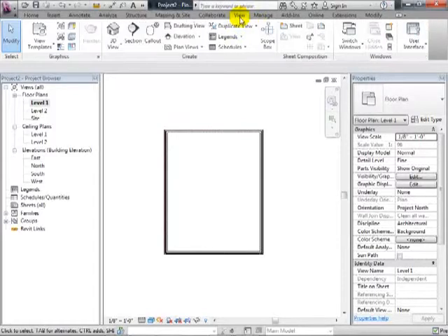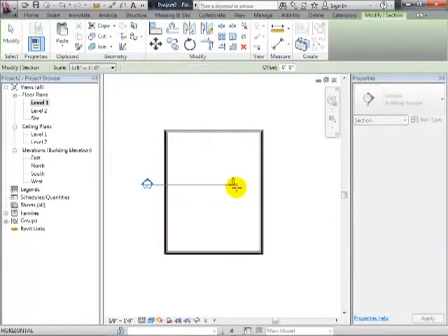If I go to the View tab, are you familiar with cutting sections? You good on that? Okay, so go to the View tab and grab that section tool. And let's just go ahead and draw, and you can draw either left to right or up and down, whichever way you want to cut your section. Kind of pull across.